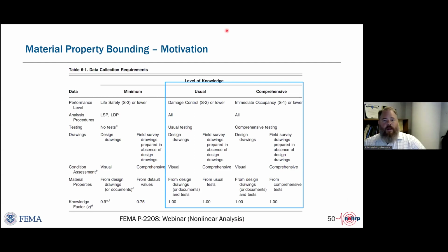And as I'm sure many of you who've created material testing and condition assessment programs know, material testing can be very disruptive and very expensive. Now, there was language in ASCE 41 that said you could defer the testing to some later time when you're validating and use that to validate your analyses, but there's risks associated with that. If you go through your entire design, assuming a set of material strengths, and then you do your testing during construction, and you find that things tested wrong, you're going to have major changes. So what we thought about was, when does it matter and how significant can material testing be and understanding knowledge of the material strength be?